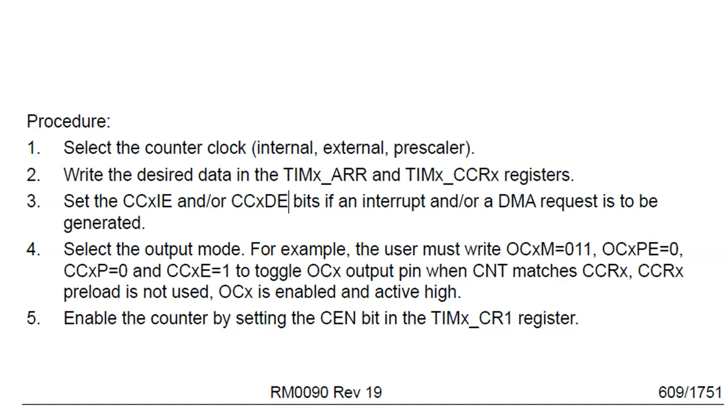For our particular case, we won't do any interrupts. Unlike the last example where we used timer 6 and 7 to drive the blue and the green LED in interrupt, I don't even want the processor involved once the timer is set up. I want it to just be taken care of without the processor having to actively go into an interrupt service routine and toggle the pin. Instead, I want to use the built-in hardware to do a hardware toggling of that blue LED, maybe the same way we did it before with a 1 second toggle rate.